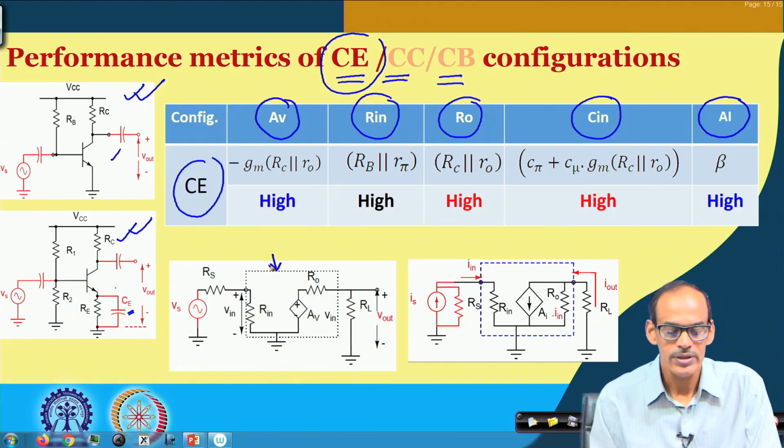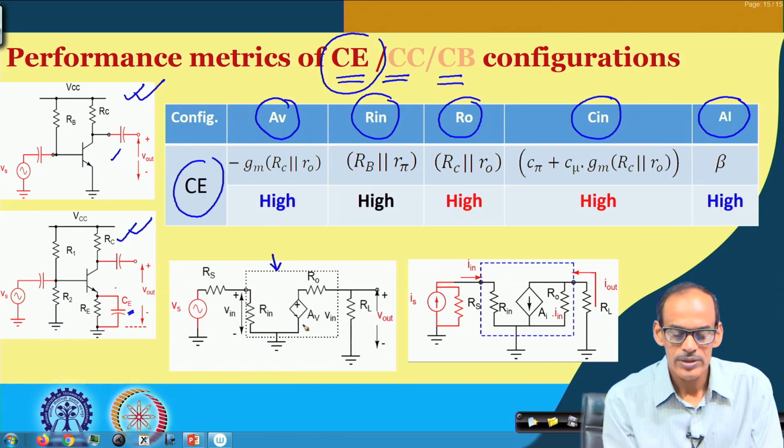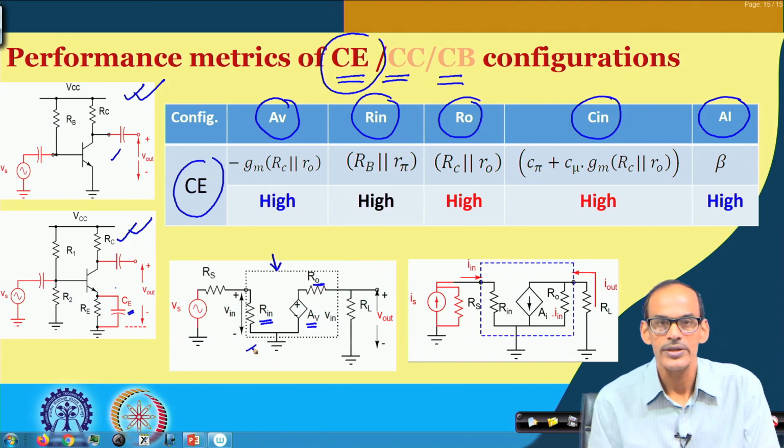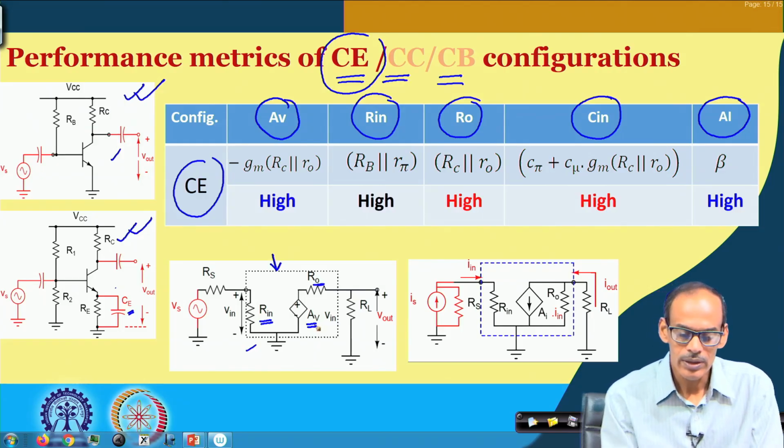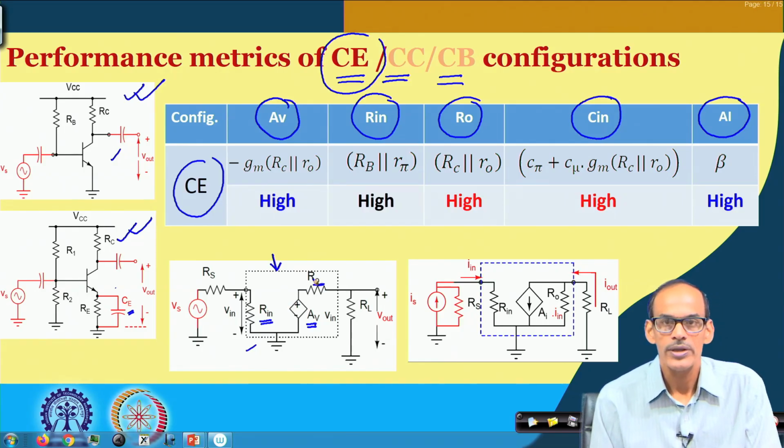This was also discussed, that whenever we translate the amplifier in the form of one amplifier, particularly a voltage amplifier, then the voltage amplifier we can model by 3 important parameters, namely voltage gain, input impedance, and output impedance, and its electrical circuit configuration is given here. So, we can say that by looking at the value of these 3 important parameters, we may certify whether the circuit is good or bad.